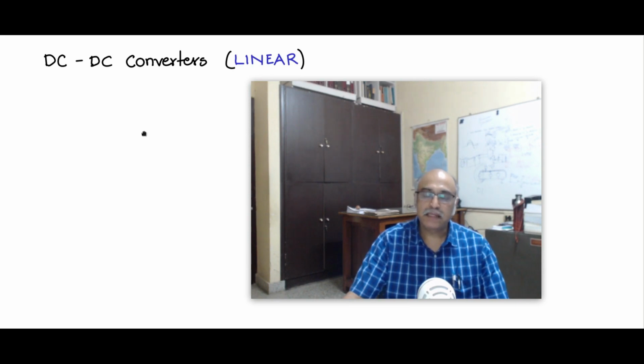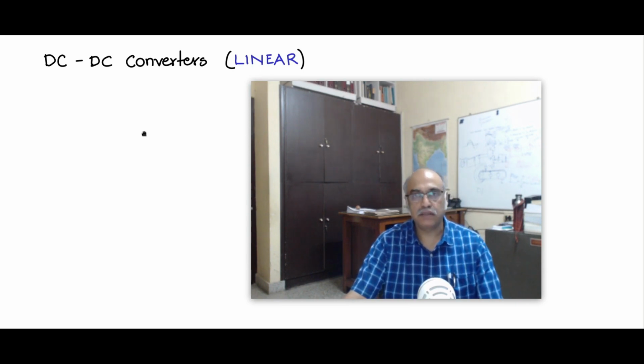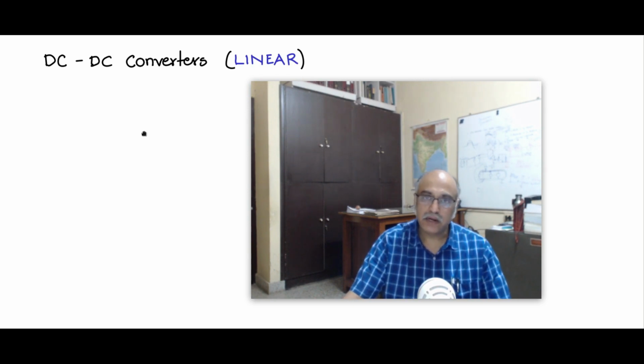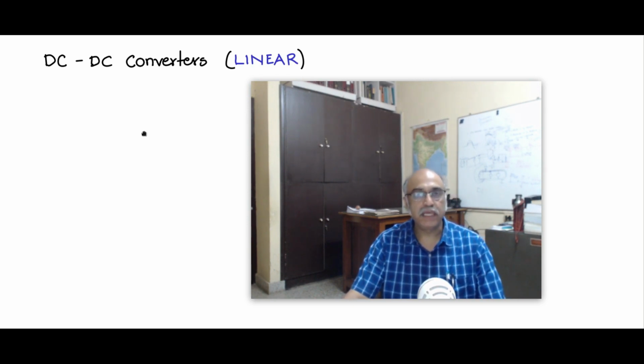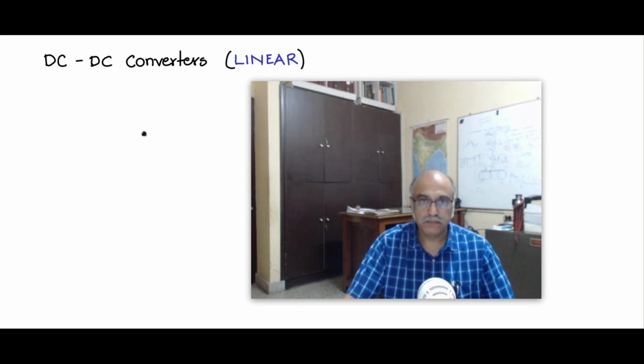When you compare the functional performance of the linear regulator and switched mode regulators, the linear regulators are very superior in terms of line regulation, load regulation, temperature regulation, and all aspects of functional performance.